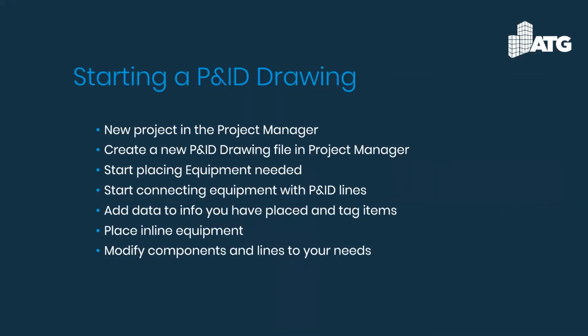All right, so next, just simply starting a P&ID drawing. I'll be getting into this here shortly, but just kind of a really quick breakdown, to simplify this. So first off, just simply starting a new project within the project manager. If one hasn't already been set up, sometimes we see some Plant 3D drawings already been created.